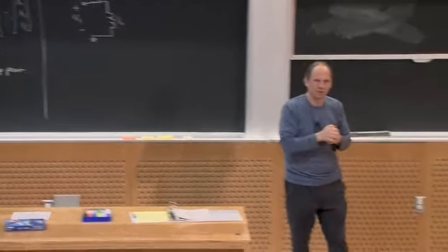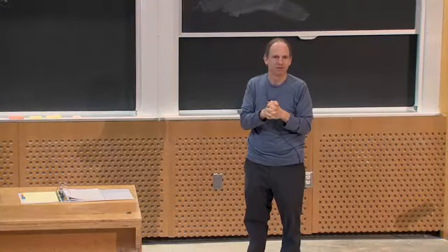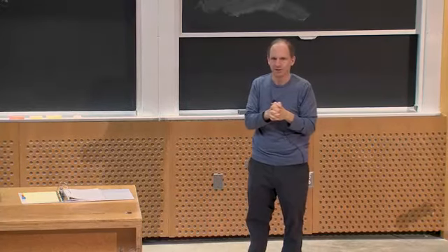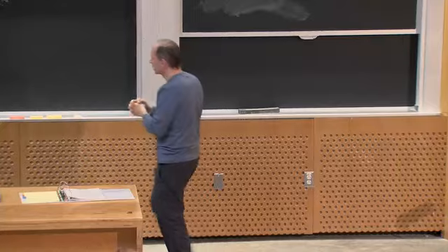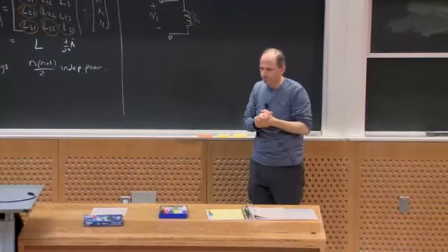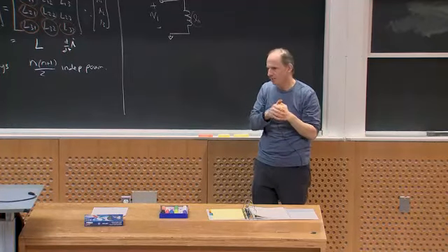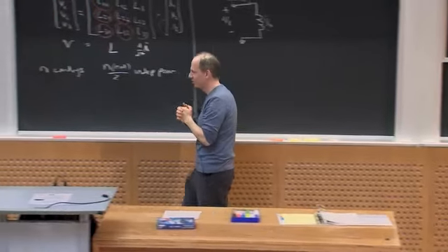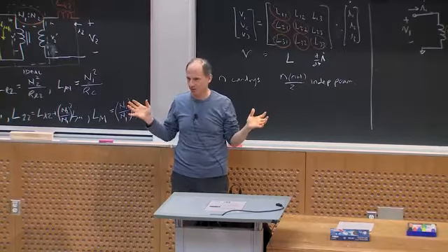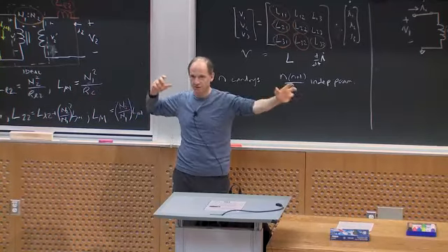How many more parameters would I need in general to model a two-port device, a two-winding transformer? 3, right? So I somehow need to extend this model so that I would have 2 additional free parameters. And if I want to keep it as simple as possible, I want only 2 additional free parameters. Again, I'm stepping back and saying I don't care if they're physical parameters. I just want them to capture the terminal relations of the device.